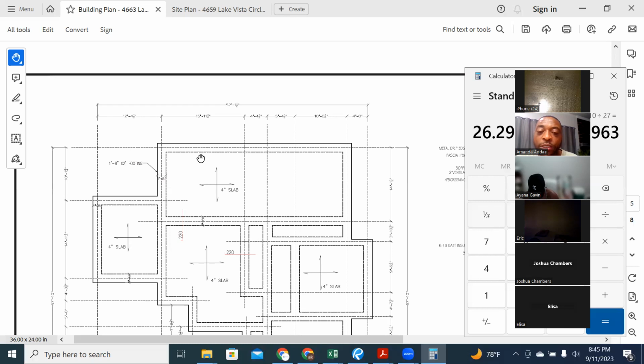So in this case, it works out pretty close because of the width of the house. So imagine this, Josh, if we had a smaller house, you know what I'm saying? I got you. Yeah. So to answer your question, it doesn't always correlate. It depends on the dimensions. And also, if somebody was doing a 4-inch slab or 8-inch slab, or in some cases, we have to raise the slab because the foundation where it is, we need it to be a little bit thicker. So we probably end up putting a 6-inch or 8-inch slab on one side. All that will be a factor.